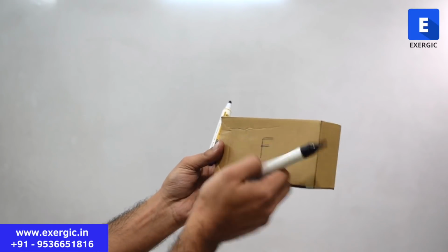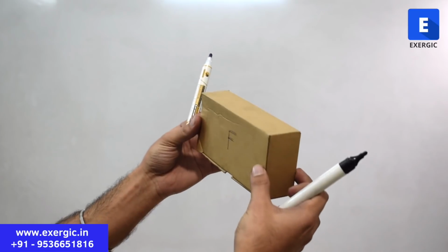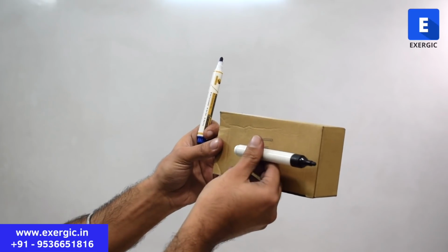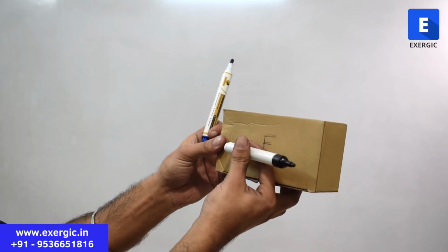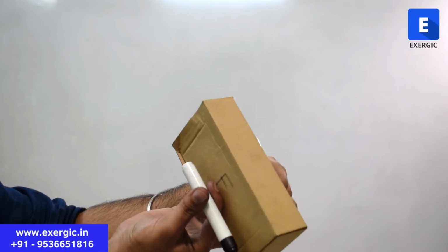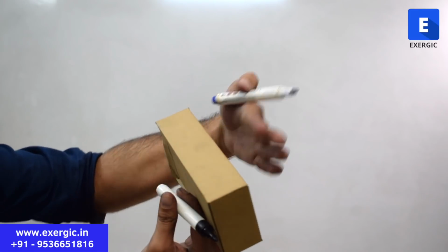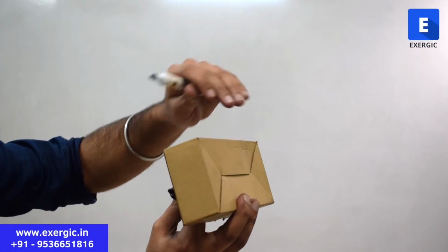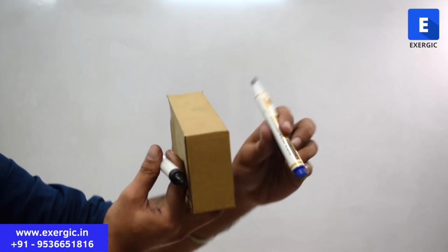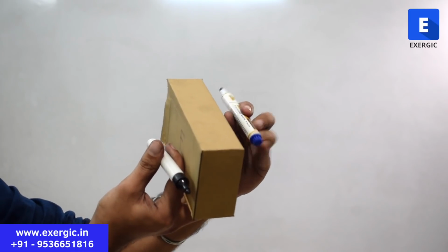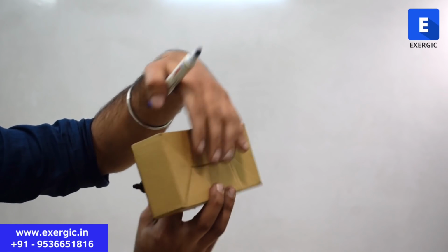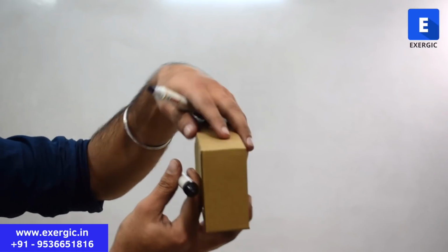Now this net force F on this fiber, consider this to be the free body diagram. So on this fiber, this net force F, due to the difference of F1 and F2, needs to be balanced by one more F force of the same magnitude but in the opposite direction. And where is it going to act? On this surface. This is the surface which is contacting the adjacent fiber. So the rest part of this cross section will exert a force F in the backward direction on this fiber. And where can it apply that force? On this area through which both of them are contacting each other.